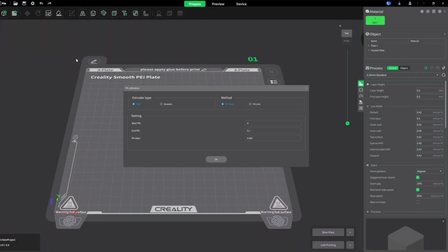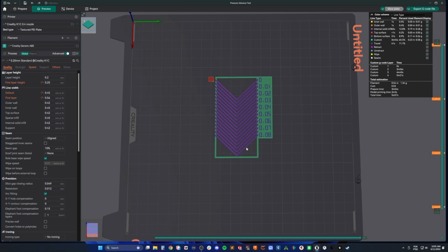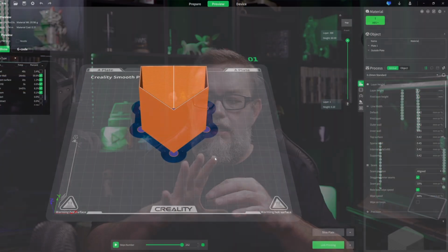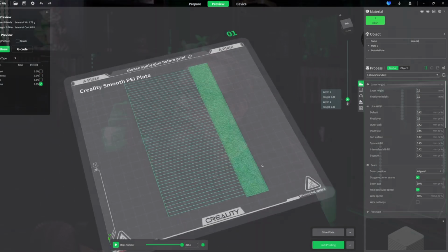In Creality Print 5, we have just 2 options to calibrate the pressure advance, and they removed one of the most interesting tests, a test that prints V lines on the bed, and then you can analyze not only the straight lines but the curves, where you can have that extra amount of filament right on the curves that makes rounded curves instead of a straight corner when you are printing your parts on your 3D printer.